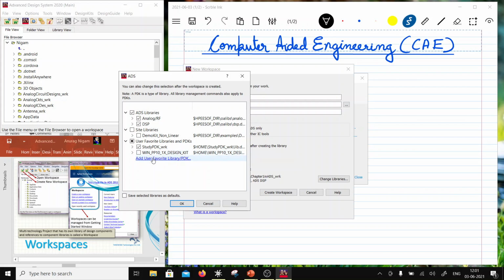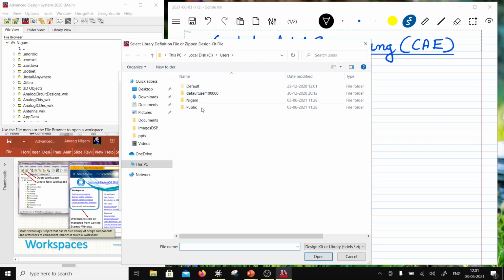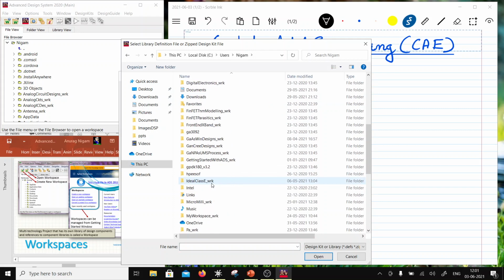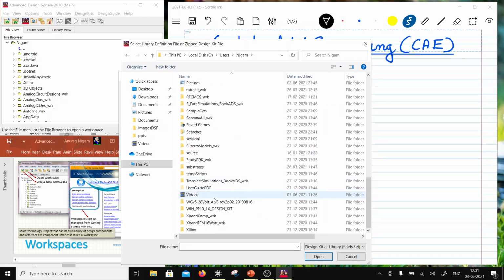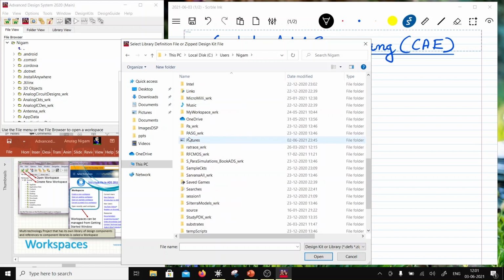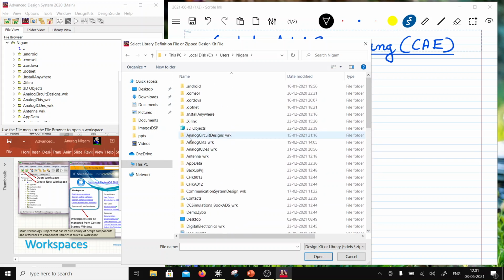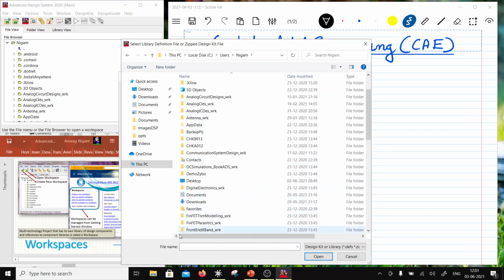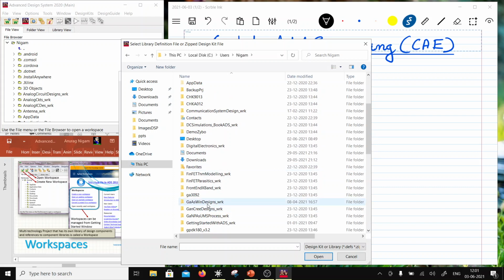Then I also have something from Win Semiconductors, which is a gallium arsenide pHEMT process. You can browse to a PDK by clicking on this link, then go to your default folder and look for your PDK. So let's say there's a Win PDK, then this one is your Cree, and then there will be something from IHP. There are different foundries which you have to sign up with, and then you'll have access to these PDKs. My PDKs don't require any signing up.